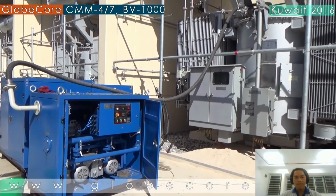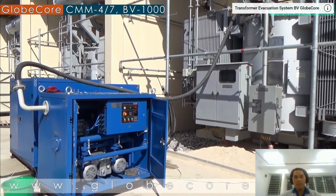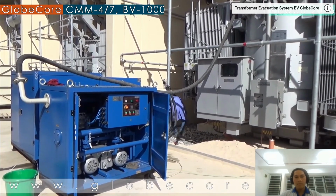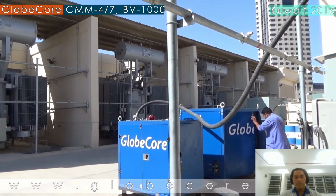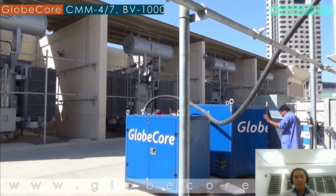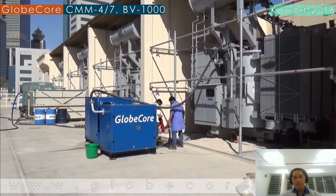The BV1000 vacuum section evacuates air, non-aggressive gases, vapor and gas-vapor mix from an airtight vacuum system at the rate of 1000 cubic meters per hour. This unit creates vacuum in transformer tanks and dries electrical equipment. The important feature of the unit is its ability to be used in combination with transformer oil degassers.